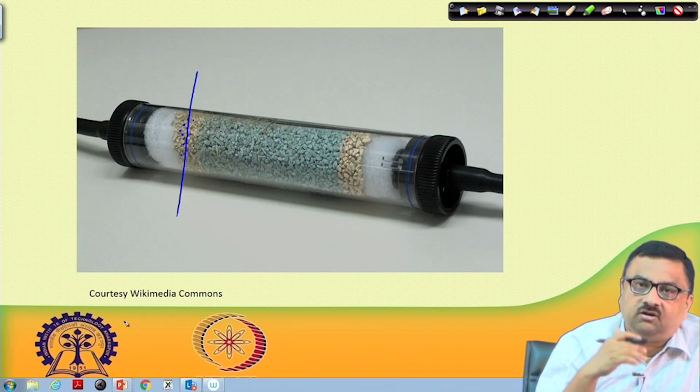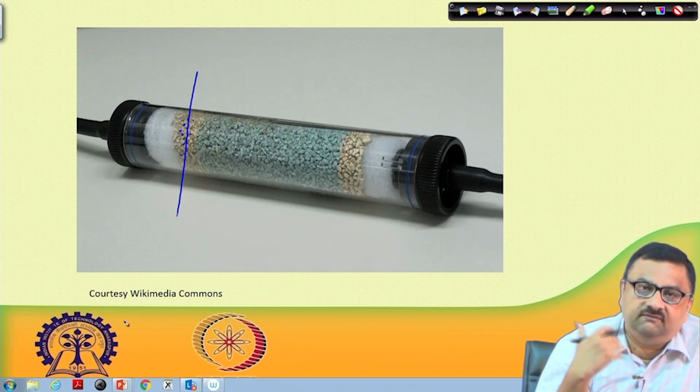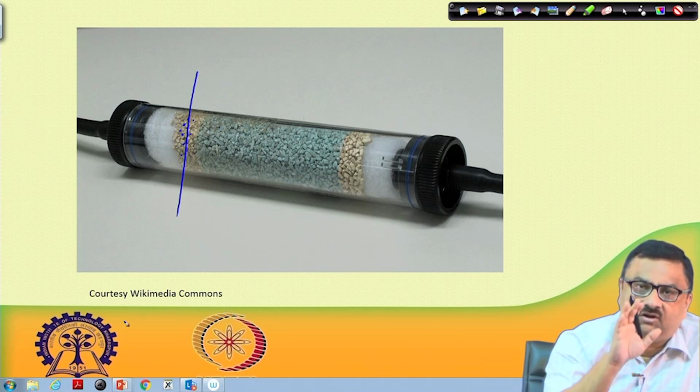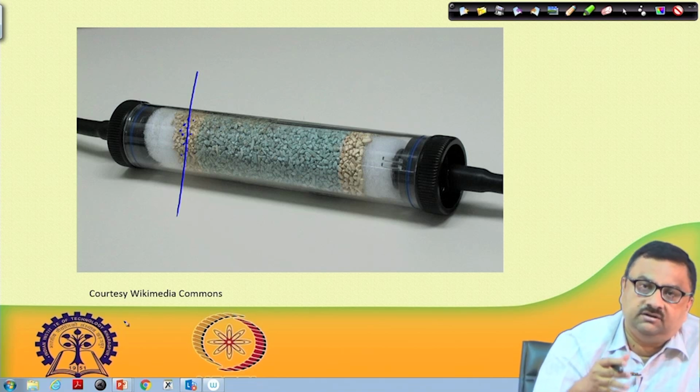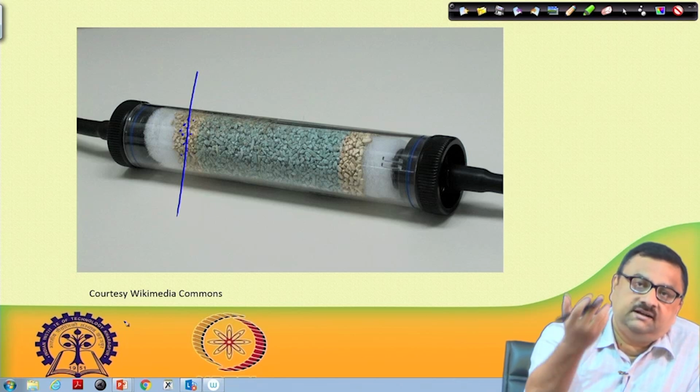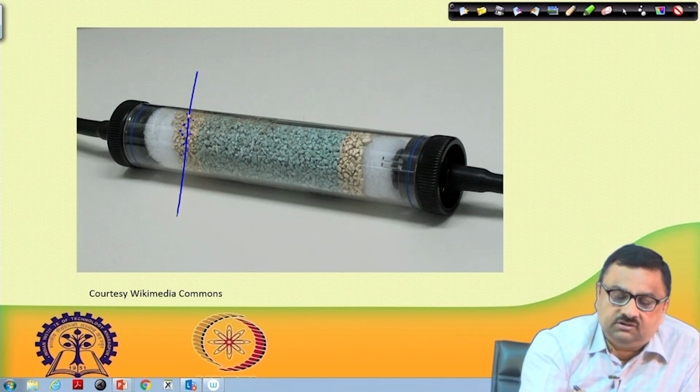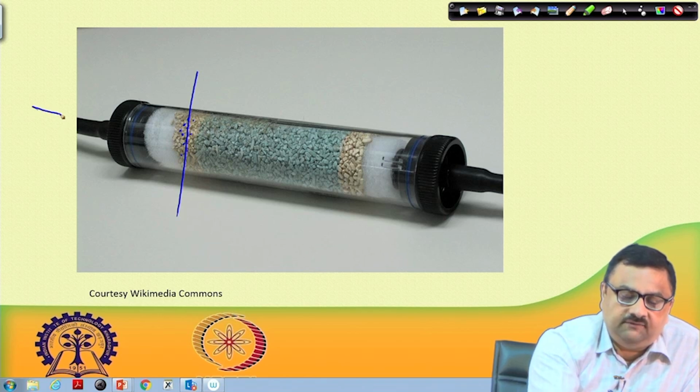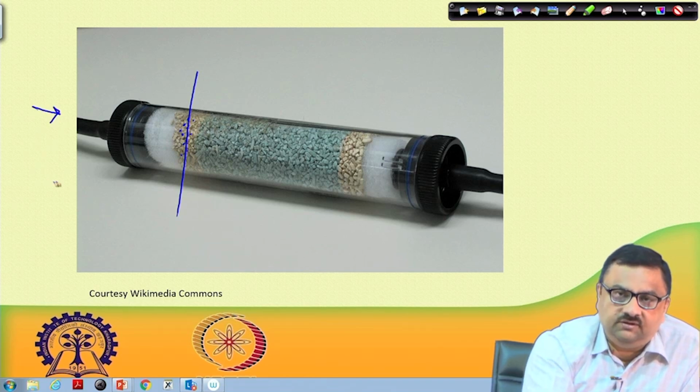Now, when we talk about sigma s dot, that means del sigma del t, how it is changing with time, and we said we are not bothered with del sigma del t, rather we are happy with del sigma s del q. At a particular location, I am having a flow. This is cumulative flow, so the flow is continuously happening. As the flow continues at a particular location, I expect sigma s to increase. At this particular location there will be more and more deposition taking place. I am having some more flow, there is more deposition taking place.